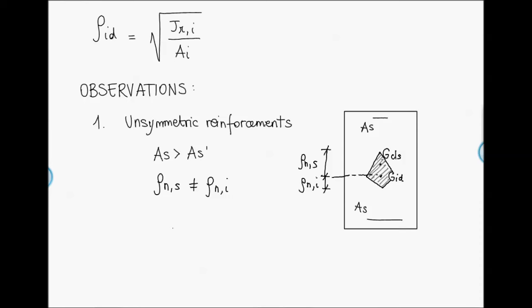The dimensions of the central core of inertia are different since the distances of the centroid of the homogenized cross-section with respect to the extreme superior fiber and the inferior fiber are different, if you remember the formula with which we have determined the dimensions of the central core of inertia.